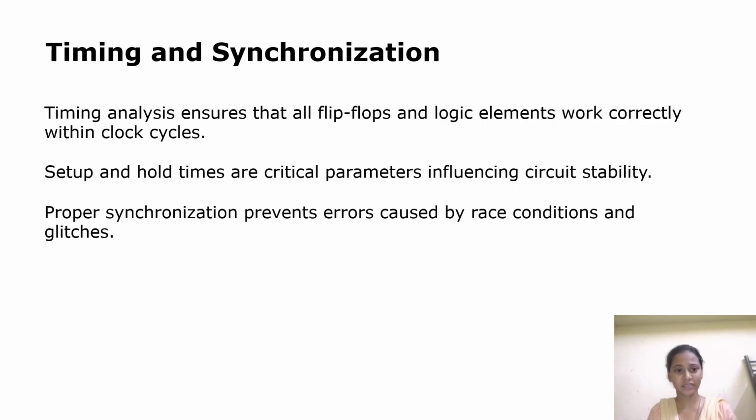Timing and synchronization. Timing analysis ensures that all flip-flops and logic elements work correctly within clock cycles. Setup and hold time are critical parameters influencing circuit stability. Proper synchronization prevents errors caused by race conditions and glitches.